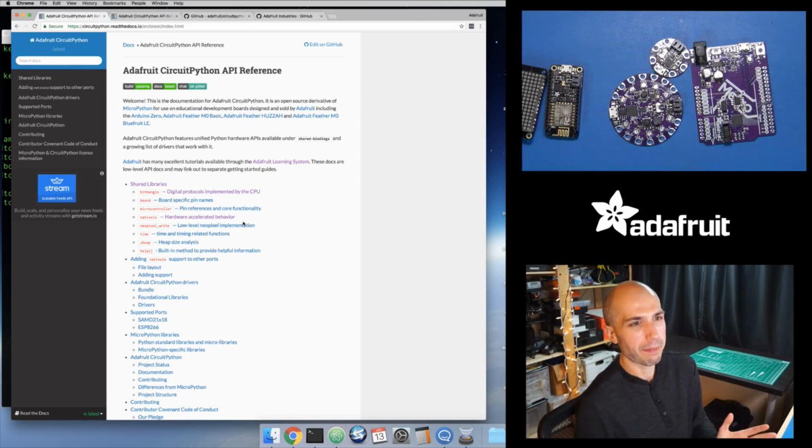It'll say, oh, I don't have the machine API, like import machine fails. So watch out for that if you're using it and you get that error. It basically means that you're trying to use code that's not written for this board, and so that's because the modules are different. And we didn't want to use the same machine module name because even within the module, the